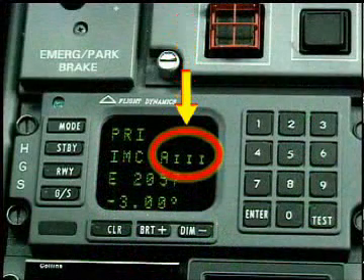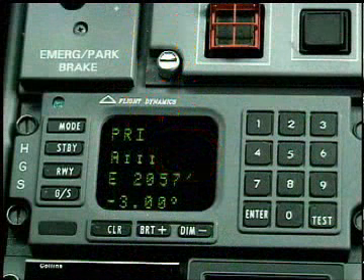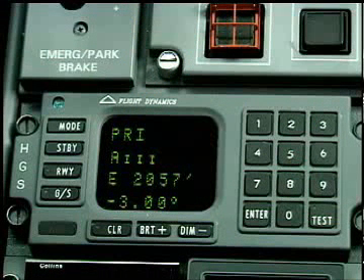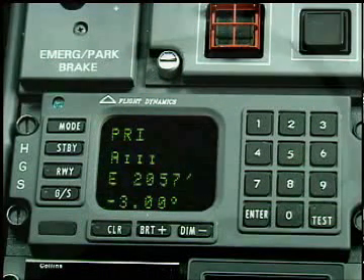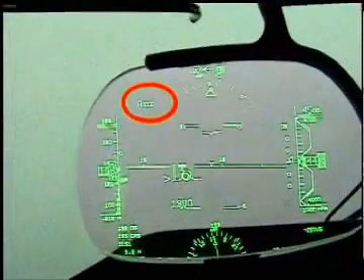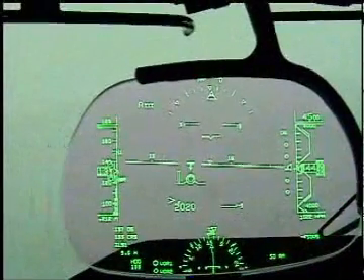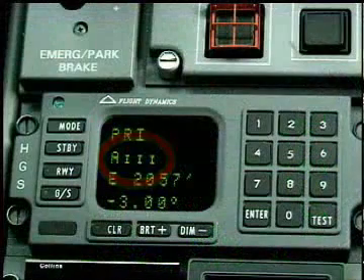At ILS capture, if approach and course logic is satisfied and all required systems are operating properly, A3 capable, the HGS will automatically enunciate on the combiner, in primary or IMC modes, and on the HCP that the A3 mode is available for selection.